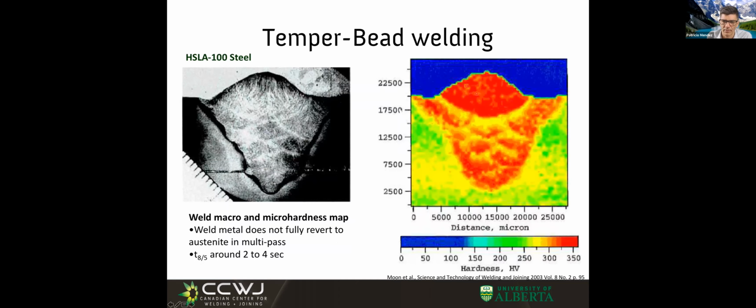Look at this. Red is hard. Yellow and green is soft. And what we see here is a weld that if you do just one pass is very hard. How do I know? I know it because the last pass is all red. It's very hard. And you would grind it off, this part. You don't worry about this. But look at what is surrounding this weld. All this was built more or less on the same conditions. All this would have been all red. But as each bead goes over, it's tempering the previous bead, and we get to see this yellow here.